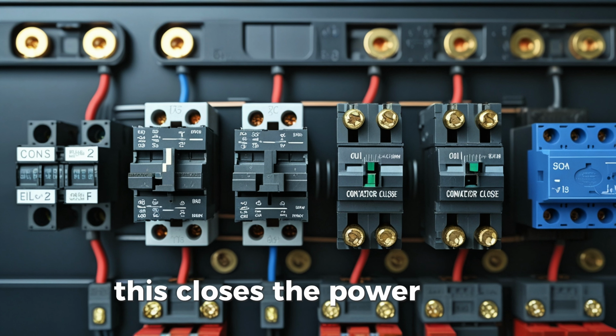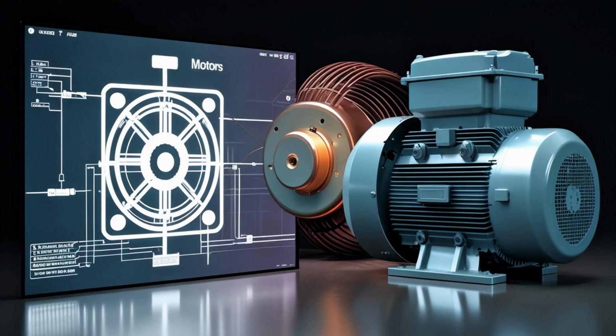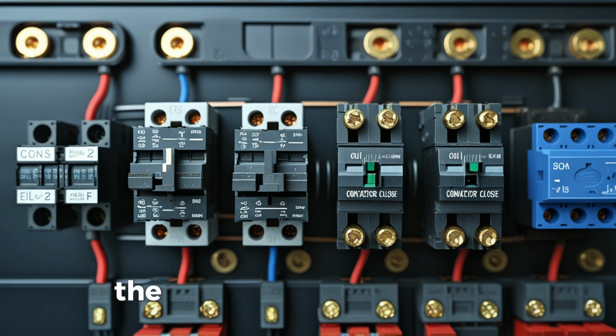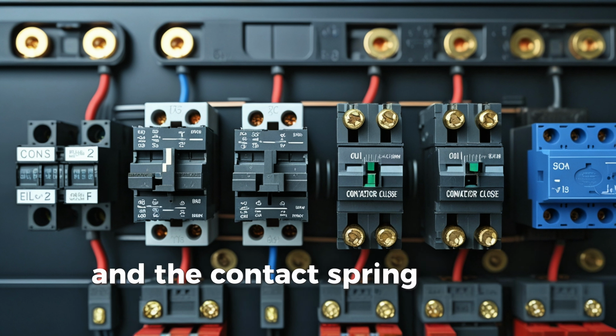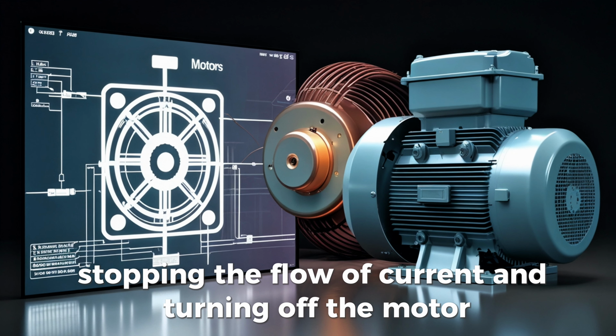This closes the power circuit, allowing electrical current to flow from the power supply to the motor or load. When the coil is de-energized, the magnetic field collapses and the contacts spring back to their normal open position, stopping the flow of current and turning off the motor.